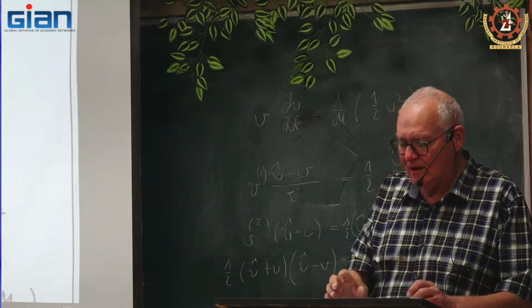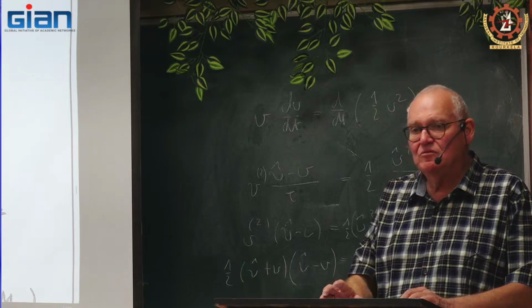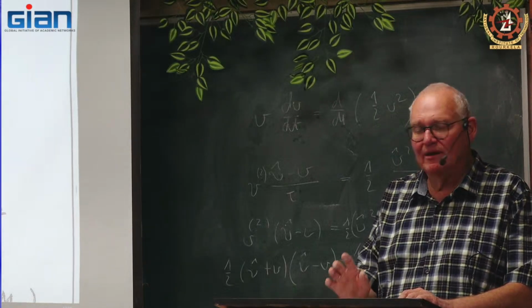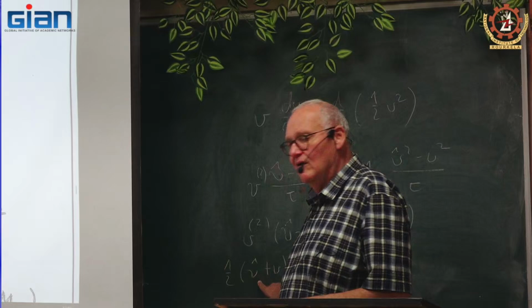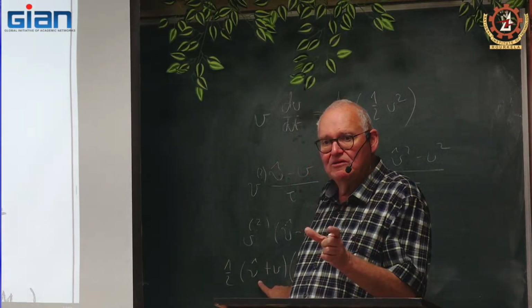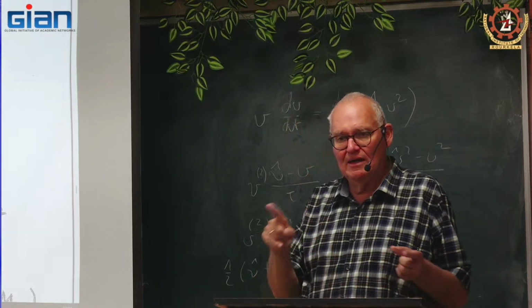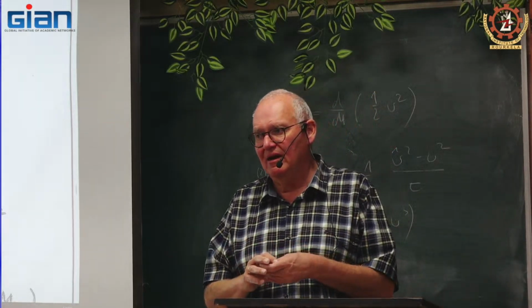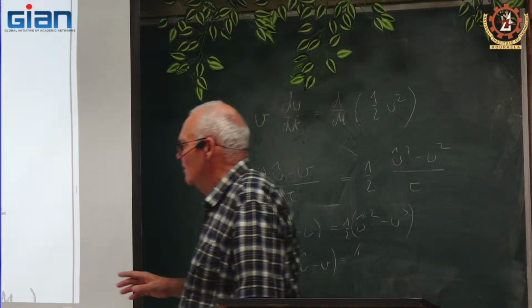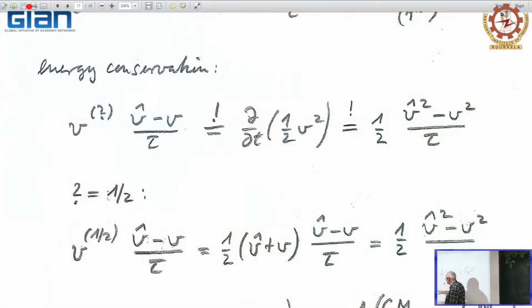In terms of the time average, this is v at 1/2. It is just in the middle between the old and new time steps, the velocity defined in between the old and new time step. So in order to have this relation, which is required once we want to have energy conservation, we have to insert the weight 1/2, or 0.5, for multiplying the velocity.